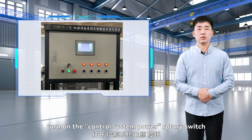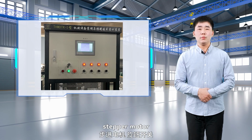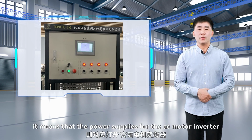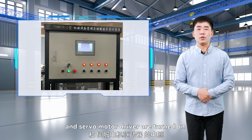Turn on the control system power rotary switch, and then respectively rotate the AC motor, stepper motor, and servo motor rotary switches to the right. When the corresponding red indicator lights for each motor light up, it means that the power supplies for the AC motor inverter, stepper motor driver, and servo motor driver are turned on.